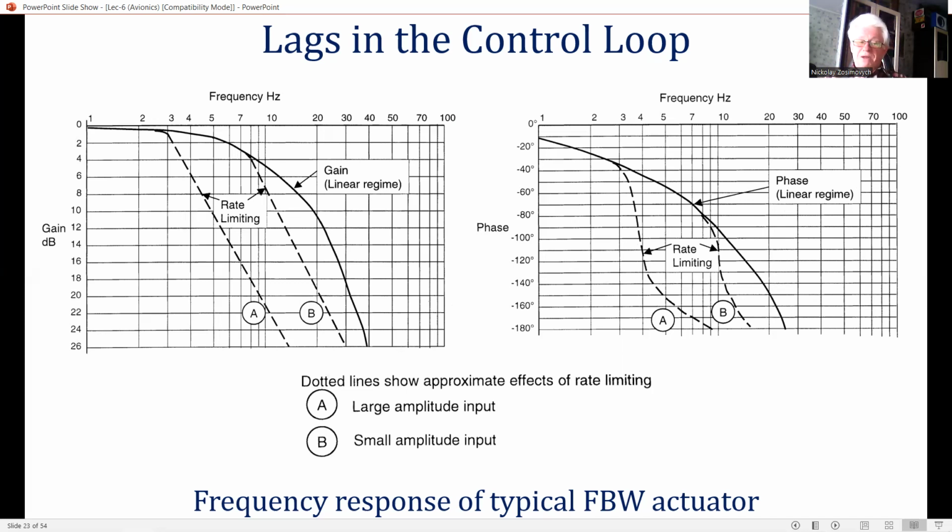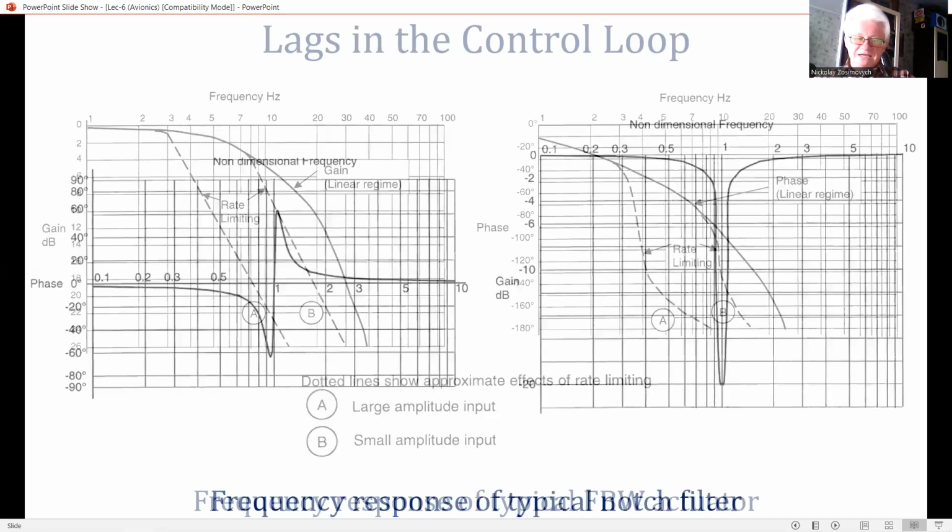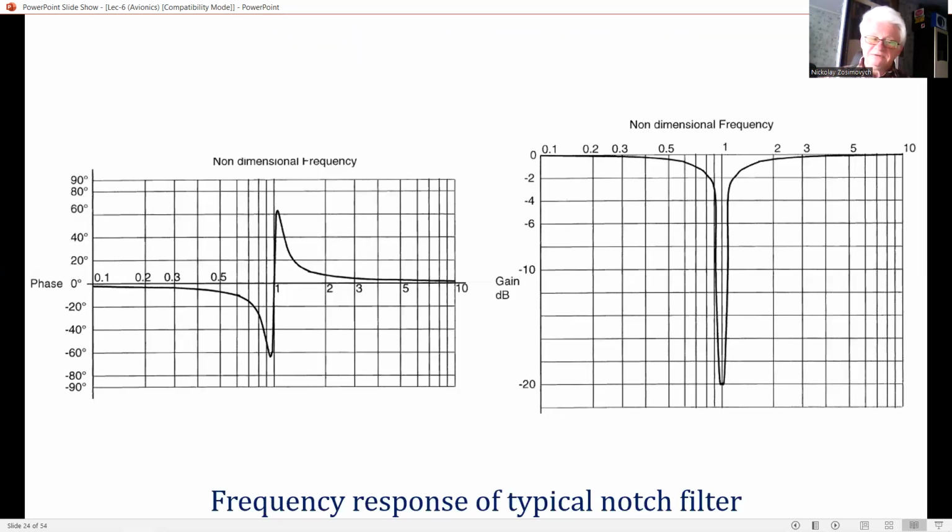Noise filters may also be required on the sensor output. These filters also produce phase lag. Next characteristic, latency. This effect arises from the use of digital computers in the processing of the control laws and sensor data. It results from two effects, either of which cause a time delay and hence a phase lag.